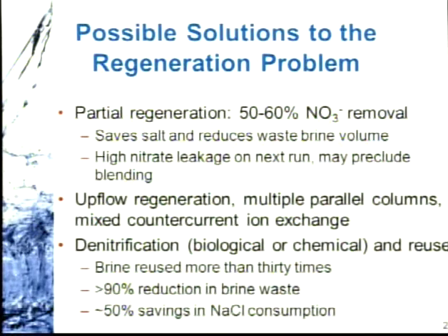This is thinking about using denitrification approaches, either biological or chemical, to remove the nitrate from that spent regenerant and then reusing that spent regenerant over and over again. That can work tremendously well if you can keep some of the other competing anions out of the equation, sulfate being the worst actor. And some have demonstrated better experience with that than others.